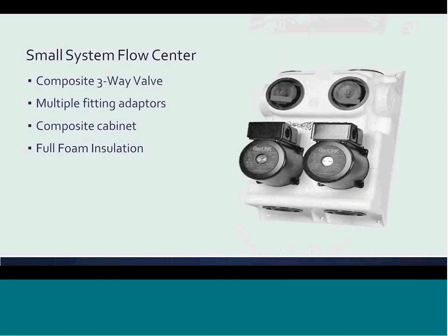We need to be able to circulate water between the ground loop and the Geo heat pumps in the building. For smaller systems, flow centers are popular and provide integrated three-way valves so that the flow center may be used to flush and purge both the ground loop side of the system and the building side of the system. Flow centers are provided by different heat pump manufacturers and pump manufacturers alike.